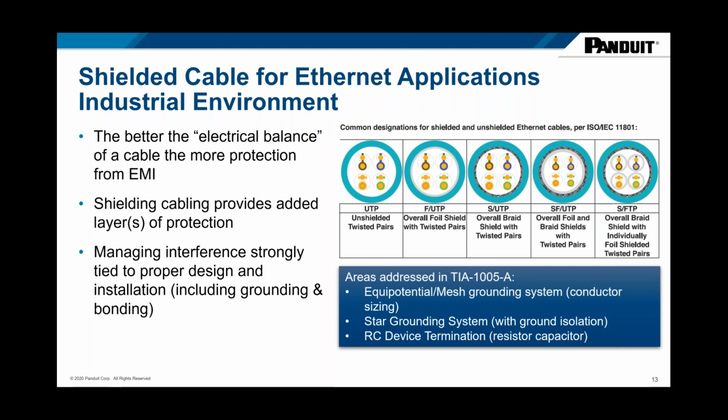And then the final piece here that kind of makes it all work is the grounding and bonding system. And really in North America, we do not pay as much attention to the grounding and bonding system as we should, right? And probably for good reason, because a lot of the grounding and bonding systems in plants are a mess and they're hard to understand and they're hard to figure out how to attach to them, right? And so we come up with band-aids for how to deal with the noise issue.